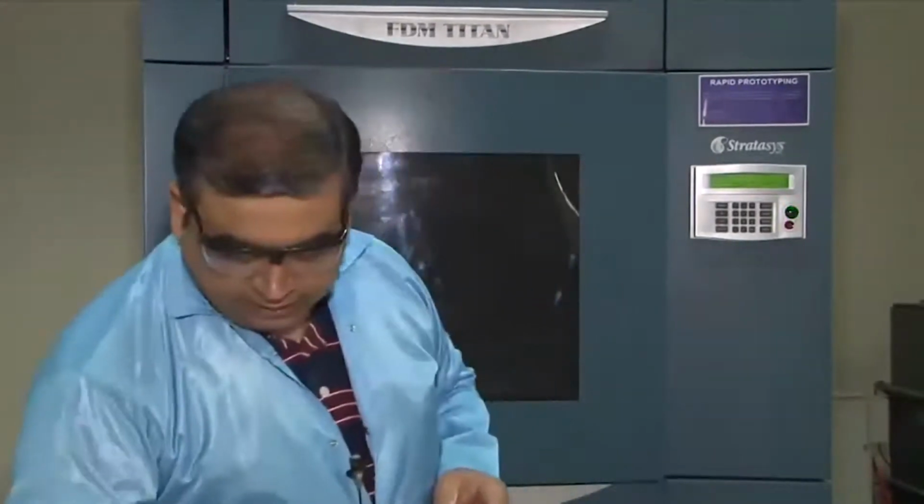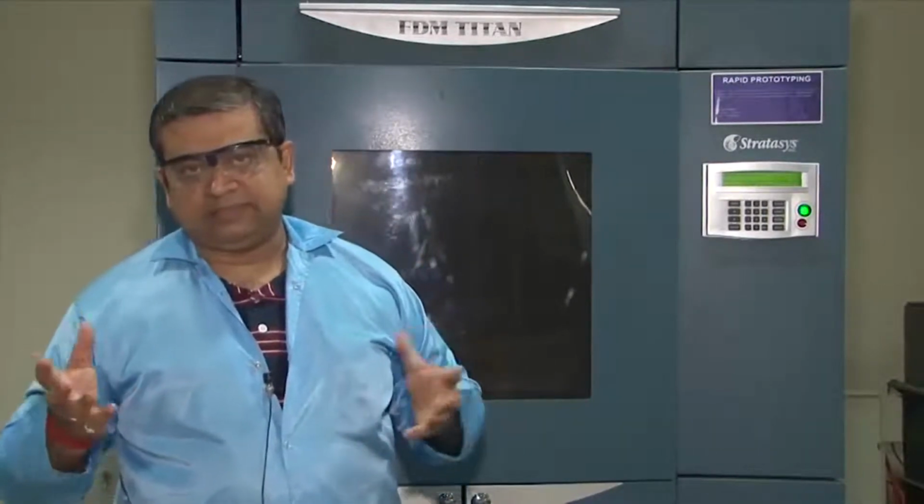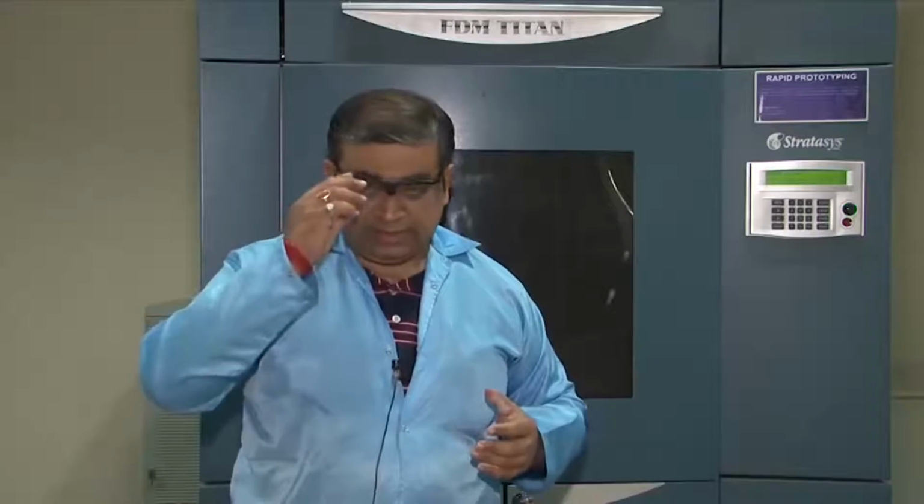Okay. So in a nutshell, what I am trying to say here is that there are a lot of advantages associated with rapid prototyping. One of them is, of course, the high level of customization. Another is the ability to handle complex designs or parts. Third is a lot of material saving because it is a layered model and there is no secondary material which is wasted in the process. And then this can formulate an intermediate process for final primary manufacturing processes like forming or casting, where probably you have to do the mold development or you have to do the die making. So some kind of a prototype is needed, okay, in order to envision and design such a system.